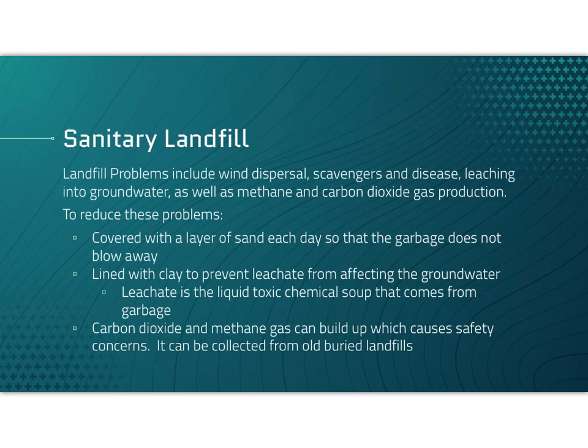A sanitary landfill. Landfill problems include wind carrying garbage, scavengers getting in there, and disease, leaching into groundwater, as well as methane and carbon dioxide gas production. So to reduce these problems, our landfills are covered with a layer of sand each day, it's permeable, so that the garbage does not blow away and is contained for scavengers.